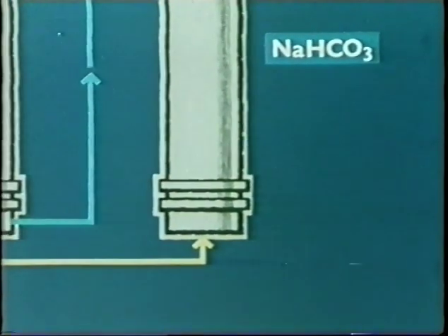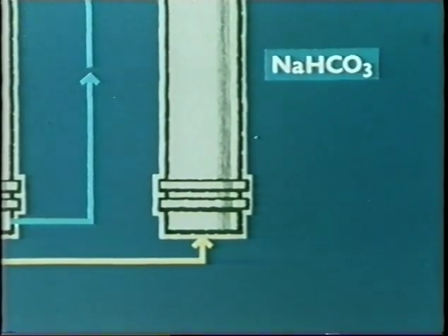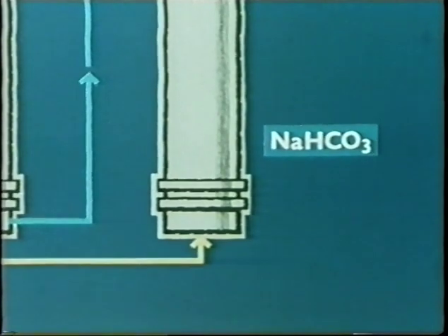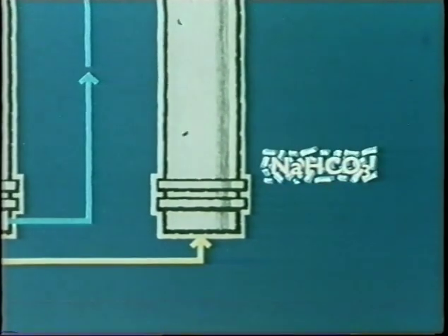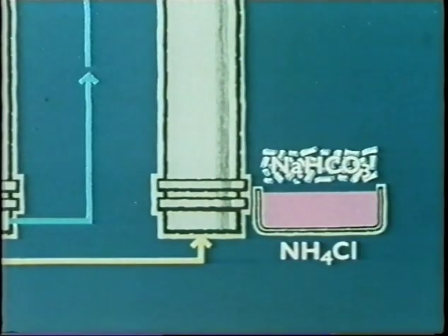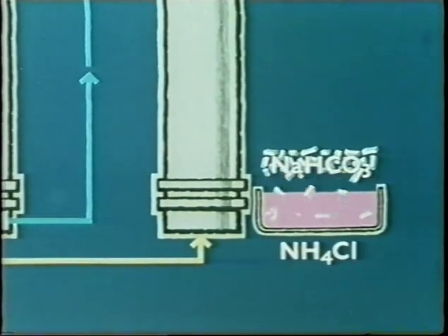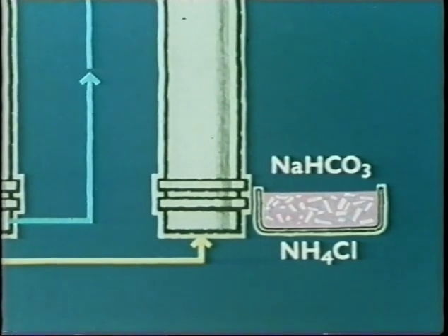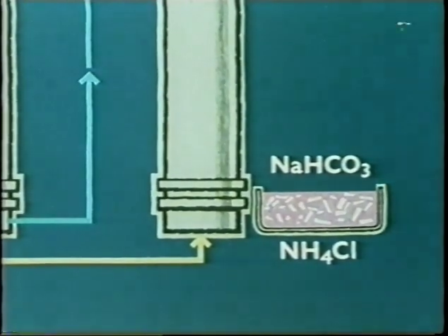This sodium bicarbonate becomes more and more insoluble on cooling, so once the bicarbonated ammoniated brine reaches the cooling zone, crystal growth is rapid. By the time the liquor reaches the bottom of the tower, it consists of a suspension of coarse crystals of sodium bicarbonate in a solution of ammonium chloride.